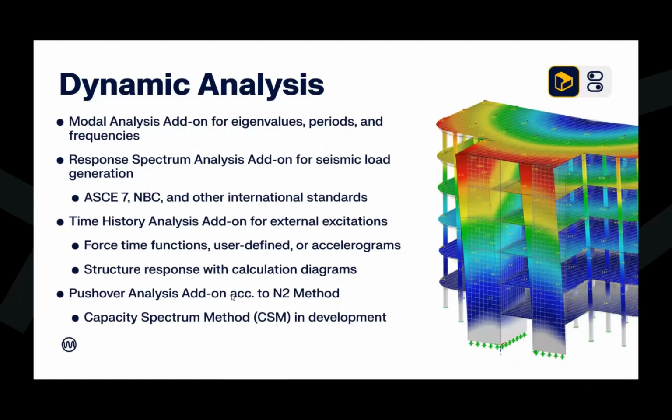So if we are interested in carrying out a seismic load generation, we would want to utilize the response spectrum analysis add-on. So within this add-on for seismic loads, we do have the codes implemented here, the ASCE 7, the NBC standard. And with the response spectrum analysis, this is applicable to any structure type. And that's why we've taken this approach with the response spectrum. Because not only is this a building program, but again, we can do these fabric tensile structures, we can do domes, we can do any type of structure for which a response spectrum is applicable.